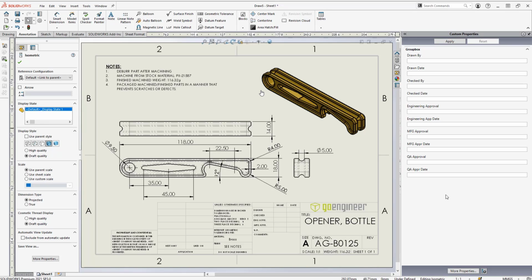This checkbox that I have set up is for my sign-off information. So the fields here will populate in the drawing title block. So this could be the drafter signing off, sends out for approval, the manager, the engineer signs off on it, you get manufacturing to sign off, and then maybe first part check with QA would sign off on it. And it saves you time. You're not editing the sheet to sheet title block to fill that out.